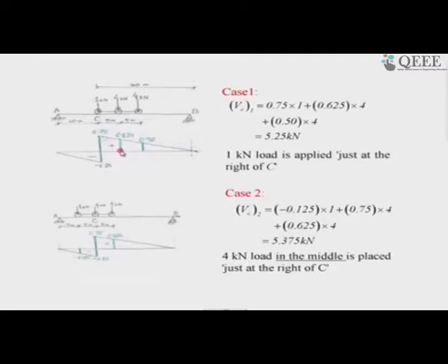You start gaining in terms of these two loads as they move towards the left. It is from here to here to here, and this load is from here to here to here. So you are gaining in terms of the positive values as both the ordinates for these loads keep increasing. For this particular influence line effect, you are also gaining in terms of the negative shear, because it will increase from negative 0.25 to negative 0.18 or so. So you are gaining here also.